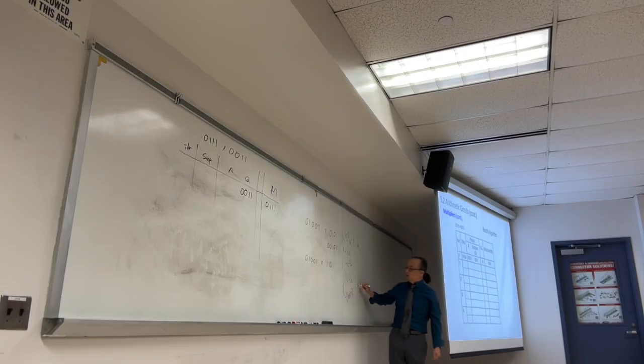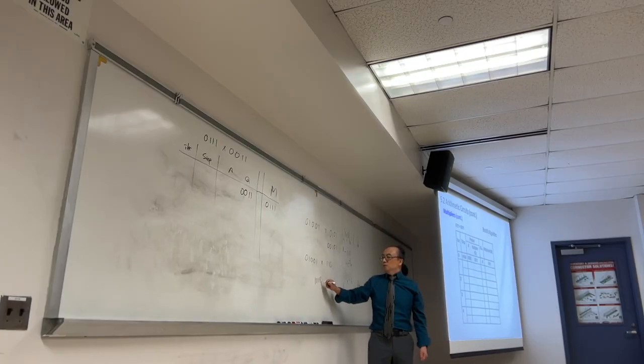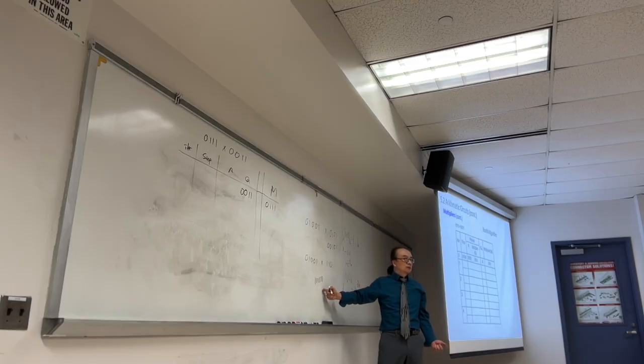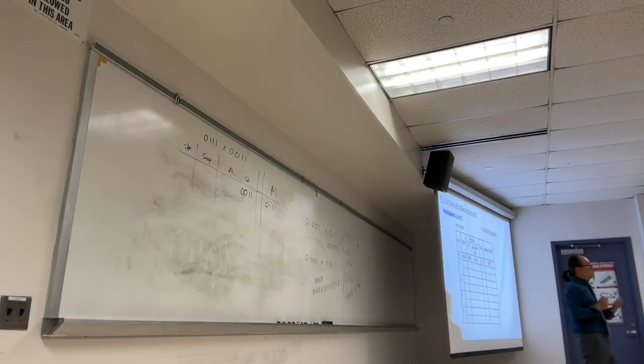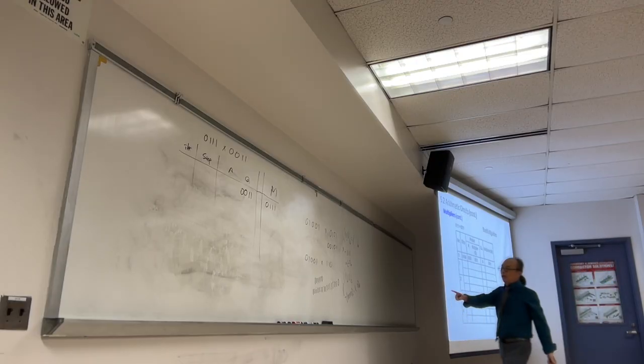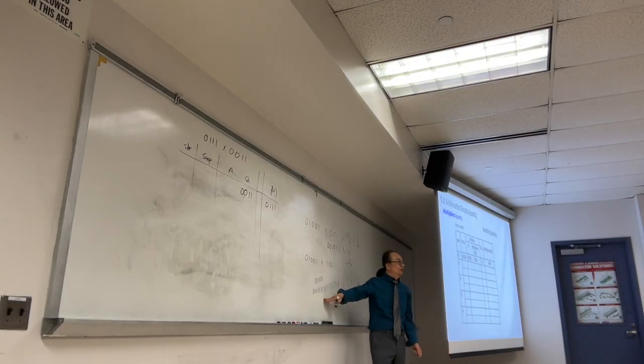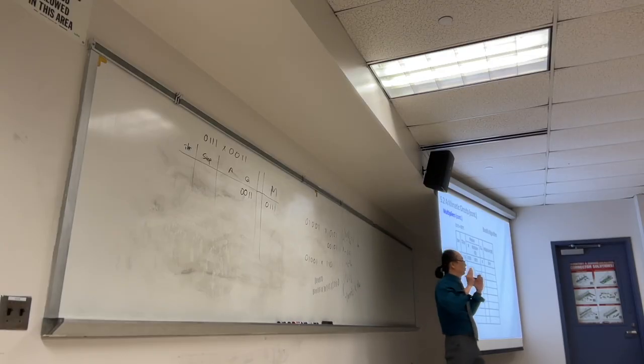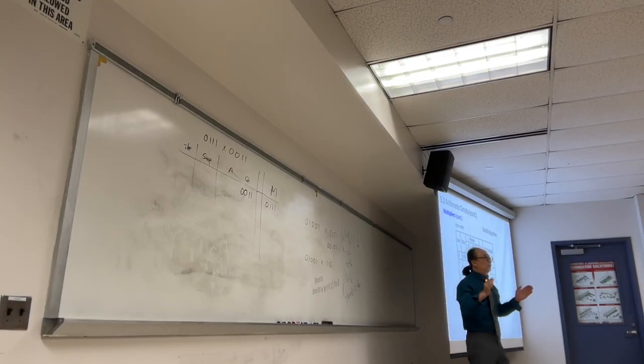So this is negative 2. Same. What about 1, 1, 1, 1, 1, 0? What is that? Negative 2. So when we do the arithmetic shift to the right, adding the sign, we are not changing the number. That is a great way to match up two binary numbers to equal length.